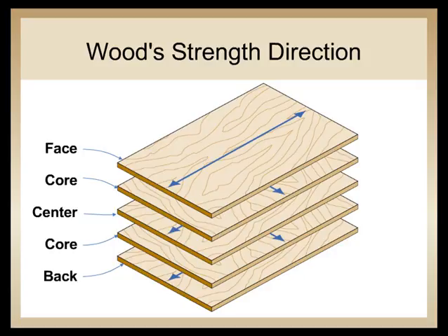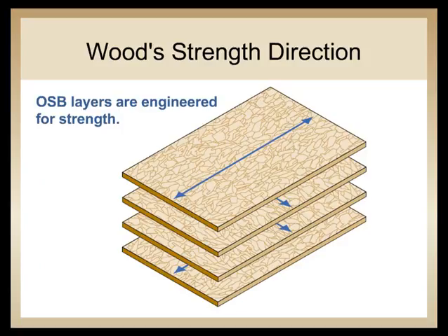The panels are glued together with moisture resistant adhesive. So having the cross orientation of the veneers as well as that glue is going to also maintain and maximize the dimensional stability, because what happens when wood gets wet? It wants to expand, and so the cross orientation is going to help resist that movement. And again, the moisture resistant glue is going to minimize how much moisture can even affect the panels.